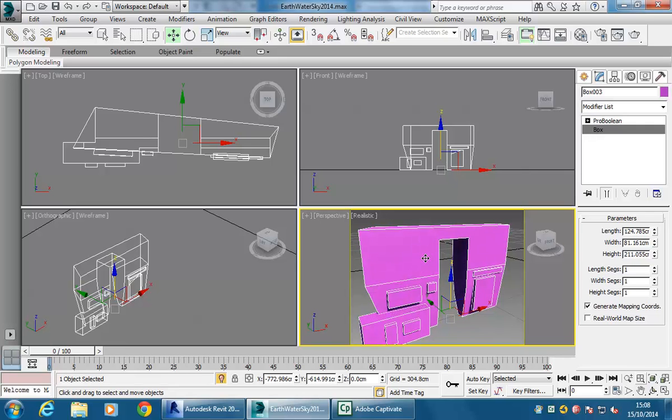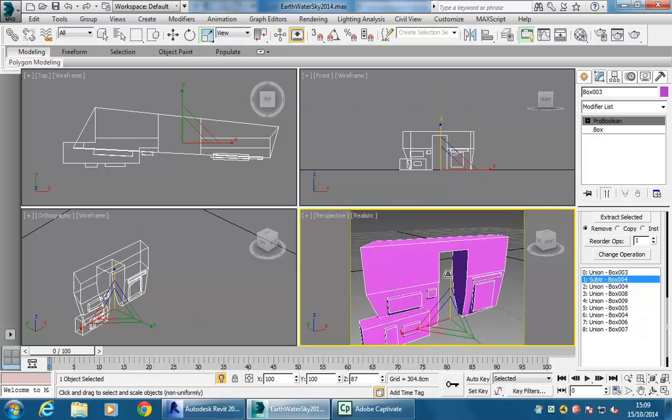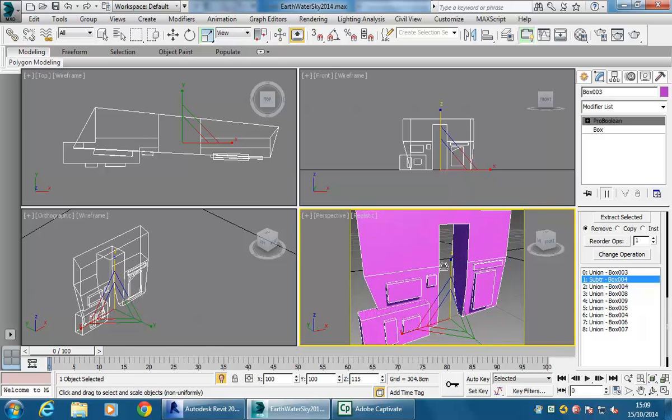What would happen if you wanted to edit that whole thing as a group, bring it all up? You would just press the final select. You can still scale the whole thing. Absolutely, I can go to scale, and if you wanted to just change the height without changing it in plan, stretch it along the Z-axis, and that will scale it up and down, and that works really well. So you're not selecting number 8 there, you're just selecting the whole thing, yeah.